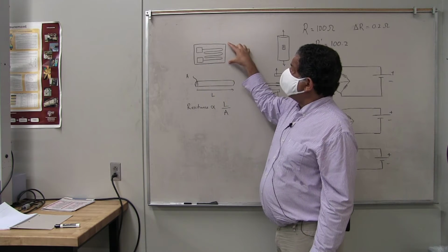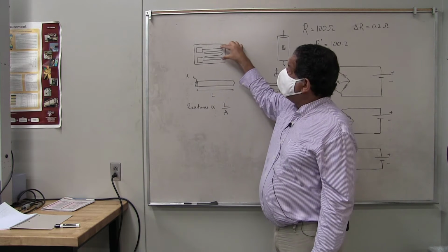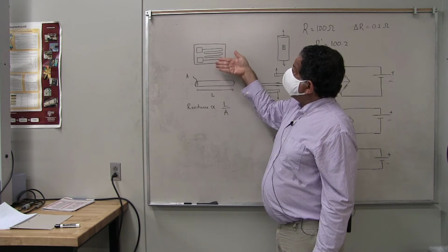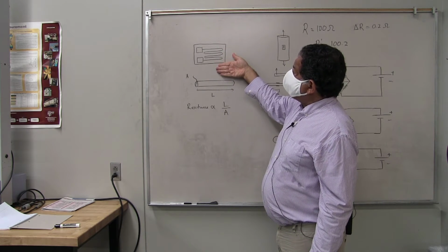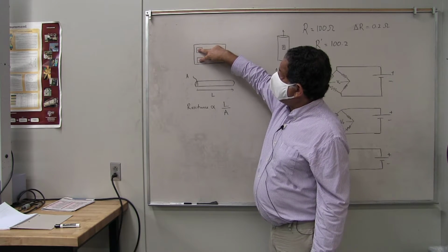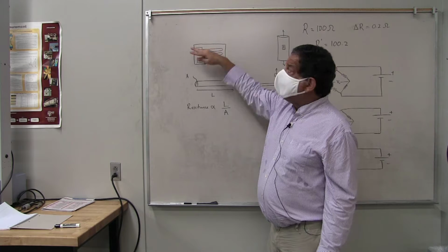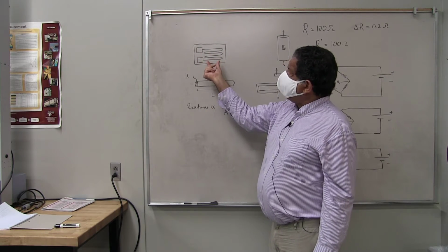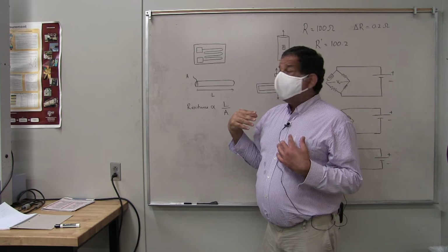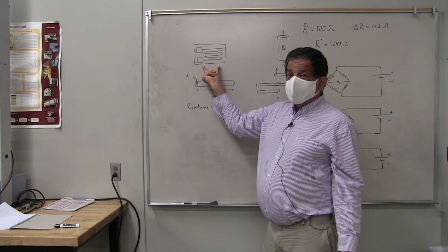material. So what we do is we take a little piece of plastic that has these wires bonded to it, and we glue that onto the surface of our material, and that's your strain gauge. And then you take leads and you attach those leads to these two pads, and then by measuring the change in resistance of the wires, you can measure the deformation of the underlying material.